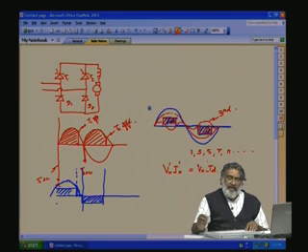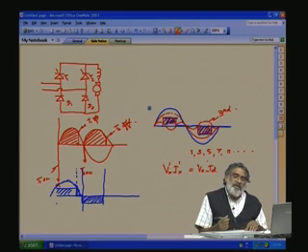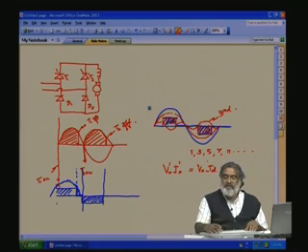Let us study how we can do it. Here we have to use pulse width modulation. This idea is taken from the communication people. The advantage of the pulse width is we will shift the high amplitude harmonics. Here the high amplitude harmonic after the fundamental is the third one. So, we want to shift the high amplitude harmonic to the high frequency side. Suppose the high amplitude harmonics we can shift to 11 times the fundamental, or 13 times, or 20 times, or 21 times the fundamental.